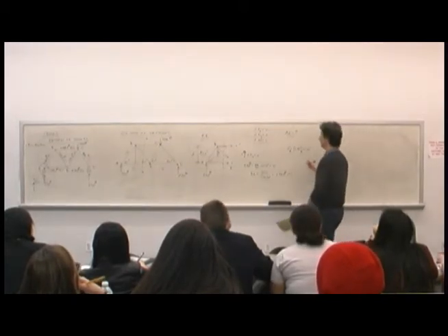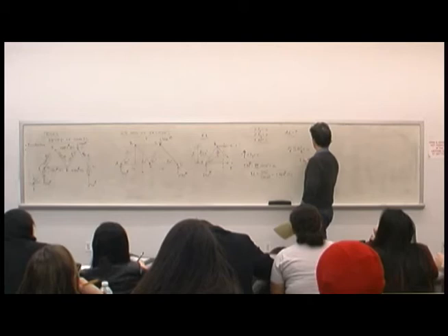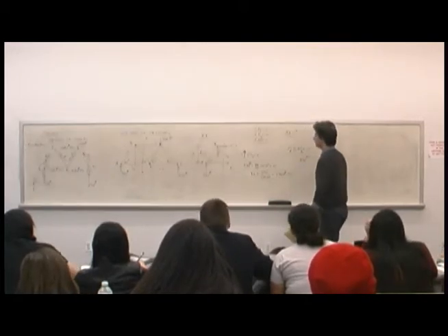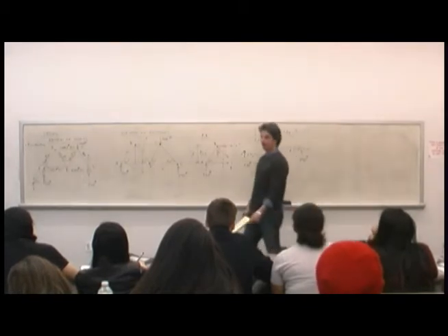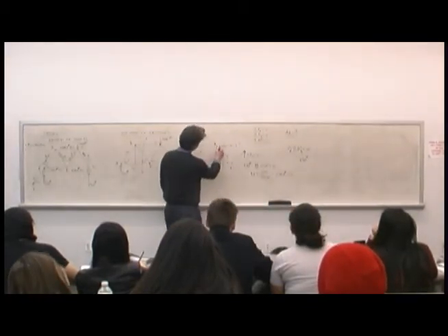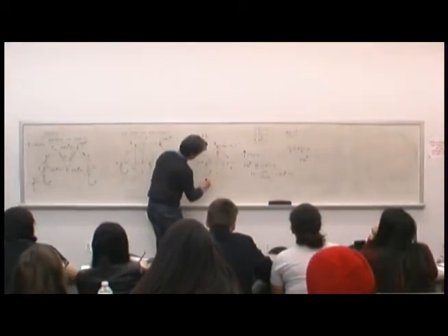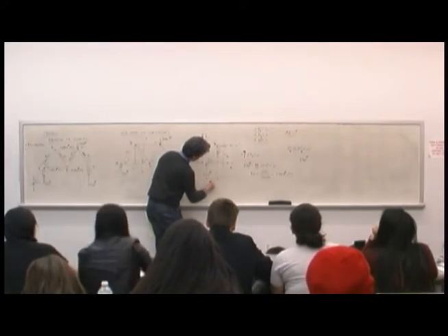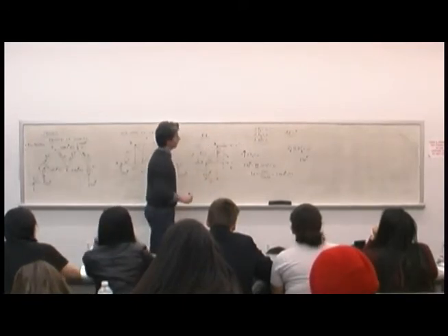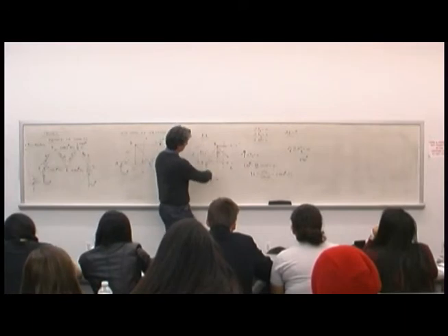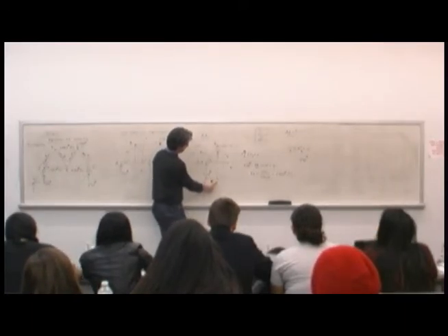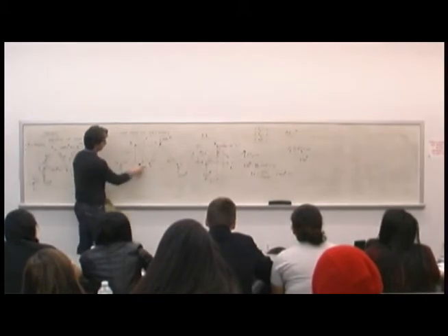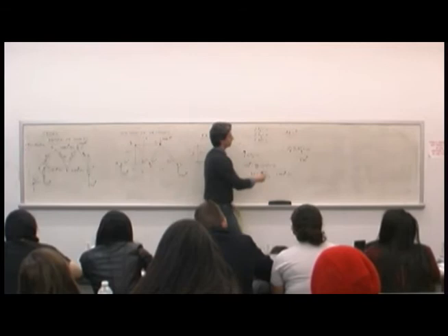Clockwise. So it's positive. So 250 pounds times what? What's the distance? Well, it's 5, but it wouldn't be negative. It's spinning this way, right? This force is going like that. So this is 5 feet because the triangle is 10, right? And that's half the distance. So it's 250 times 5.